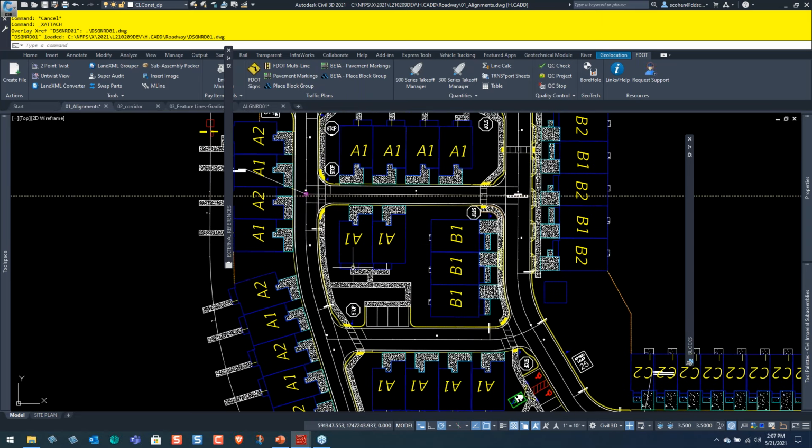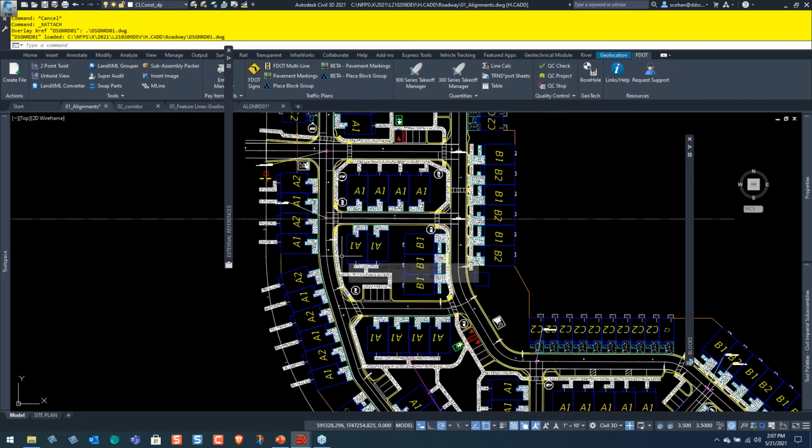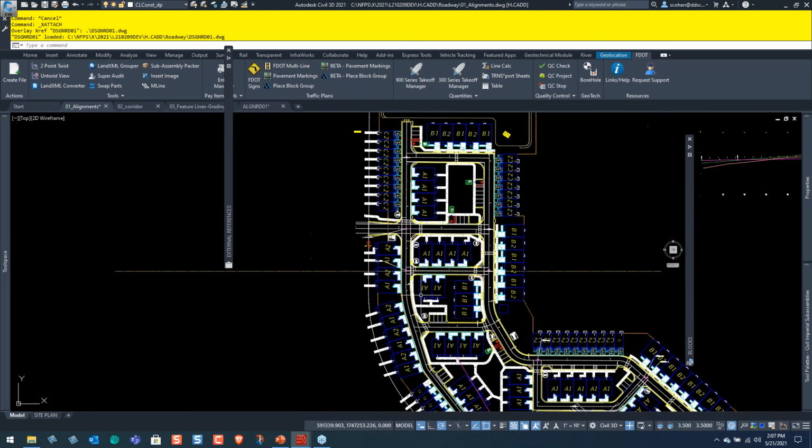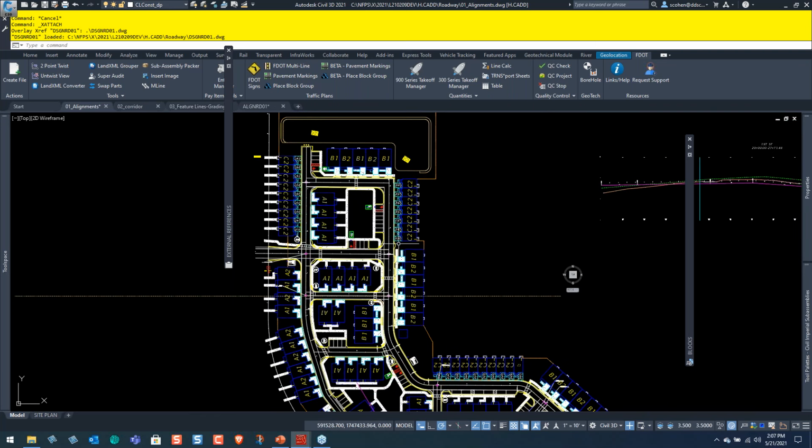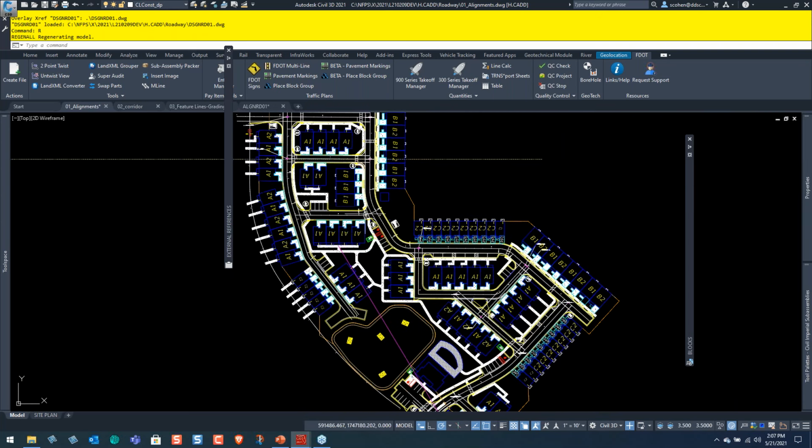You can see it's really quite an involved project, as well as we have sidewalks and buildings and all that good stuff. So one of the things when you're doing site design is you figure out, the first thing you do, where's the water going to go? How many ponds are you going to need? You do a general idea of things. And basically what we figured out was, here's the high spot of this site, existing wise, and the natural flow of the water. So we have a pond going this way because we have a watershed this way, and we have another watershed this way. As you can see, this one's a little bigger. We got the ponds a little bigger as well.